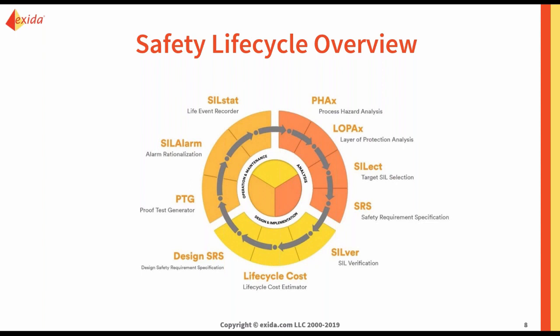Finally, in the O&M phase, you want to keep track of your plant performance, your safety instrumented system performance. So this means keeping up with your proof testing, your routine maintenance your devices require, as well as any device failures or demands on the process. All of this information over a number of operating hours is going to give you plant actuals that you can use to either validate your analysis, validate your design, or feed new analysis and design for a greenfield system.